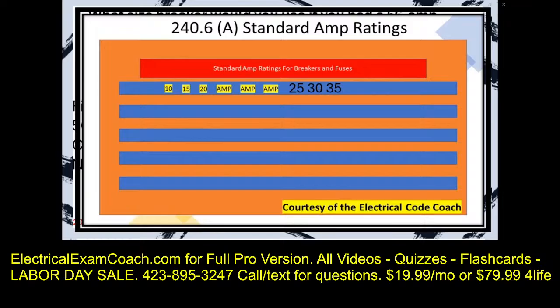And that's where I want to take the time right now to point out that you should always go to the table and verify the size that you should choose. This is where you can let field experience burn you when you're in the testing center. Because if we're out in the field and we see a 34 amp load, we might put that on a 40 amp breaker. So you might see a 34 amp load inside the testing center and automatically assume that the next size up is 40.